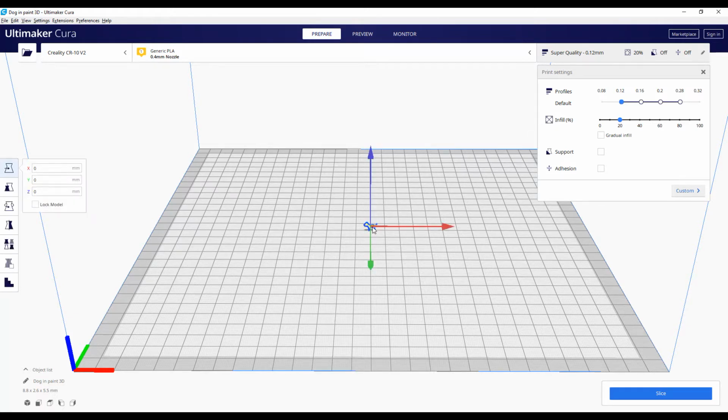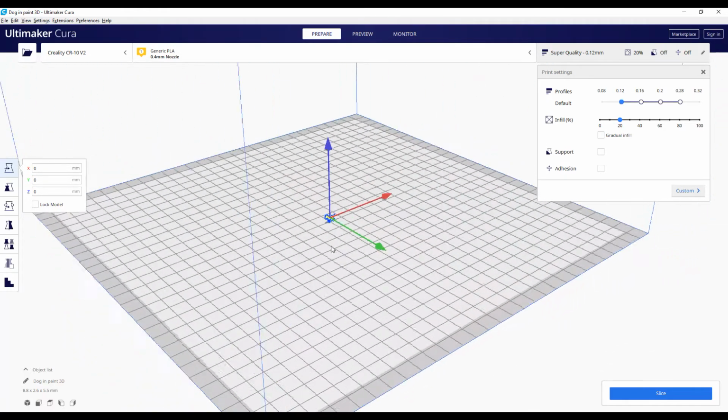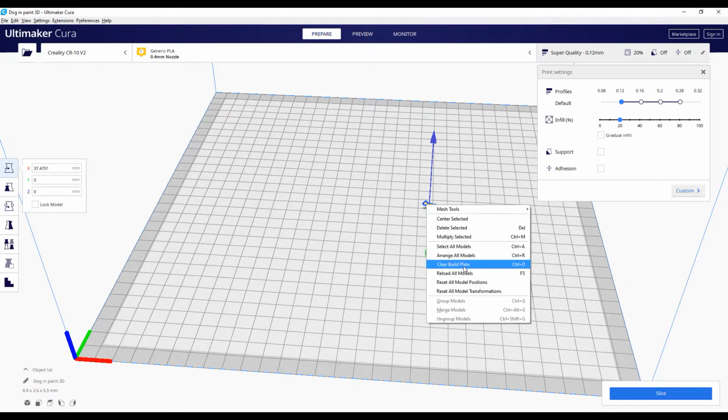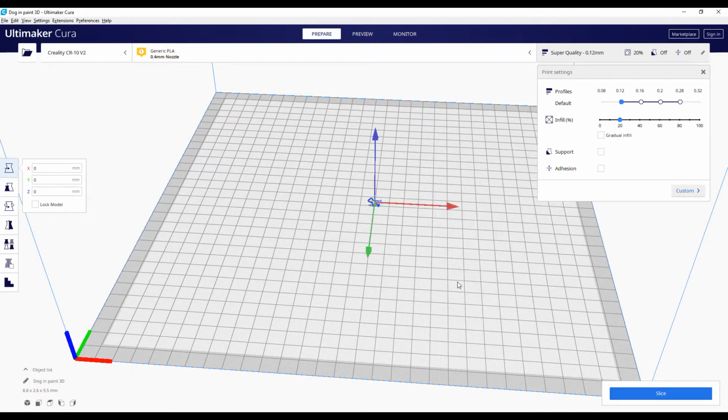So when I have the object, I can click on it, and then with this panel, I will have the possibility to do some things on the object. And of course, the first thing is by using this to move the model. If I want to undo this, of course, Control Z, or simply reset all positions after a right click.